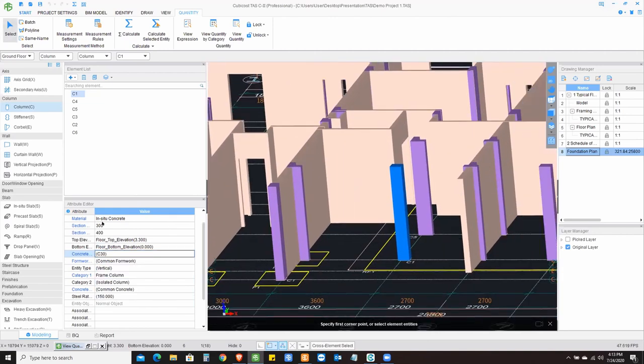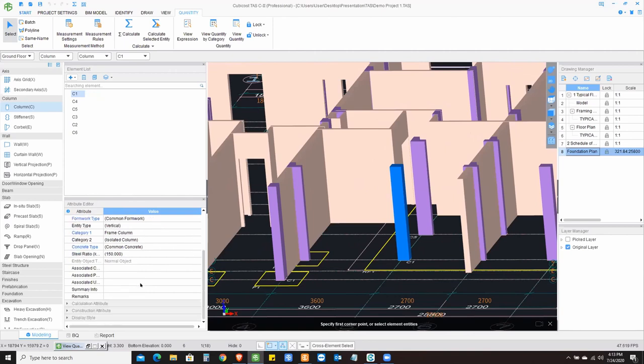Post-contract cost management. Okay. It's a big topic, but I can choose maybe a few functions to show. There are ways of doing it. Like I said, you can set up the actual start date, scheduled start date, actual end date, scheduled end date, all of this for different subcontractors, flow zones, all of this setting here.